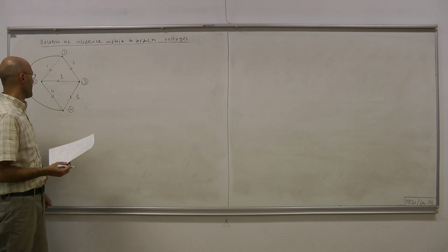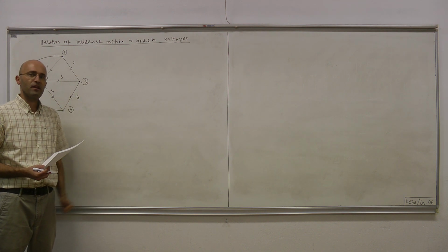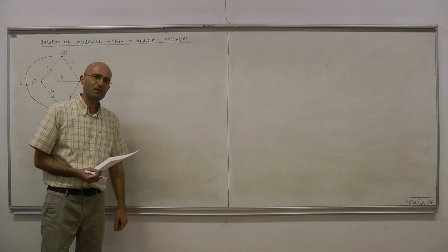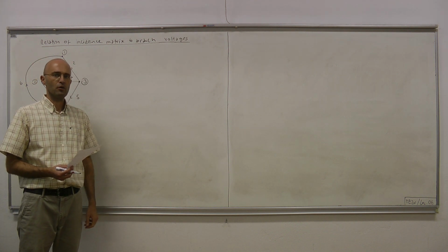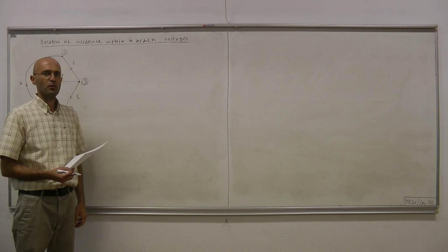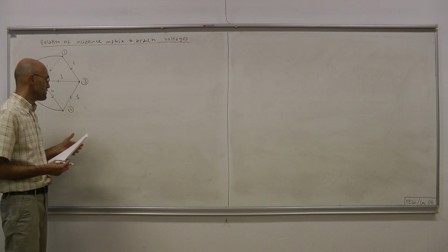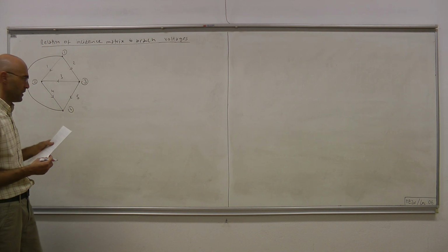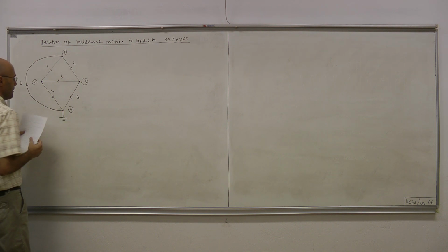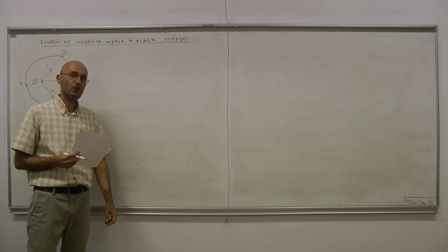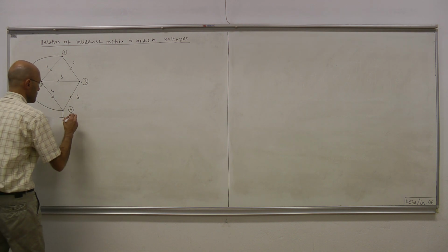Then if you write KCL, which we did, at all 4 nodes, and express what you obtain using a matrix, the incidence matrix appears, and we saw that the rows of that incidence matrix are linearly dependent. Therefore, that representation is not minimal. To make it minimal, we removed one of the rows corresponding to an arbitrary node, and that node was the 4th node in our example. To indicate that, let's put this ground sign, so that we know that this is our reference node.